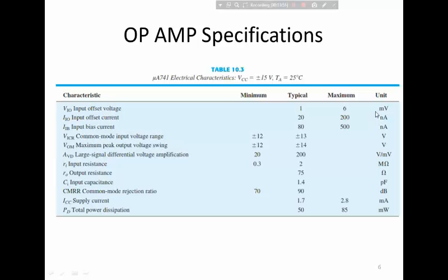Specifically in the open loop gain, you know that even an input error voltage of a microvolt can bring the op-amp into saturation, and a very large output can be here for a very small input. So input offset voltage has a very significant effect on the output. So it is important to see whether the op-amp's output is due to the input offset error voltage or because of the desired input.